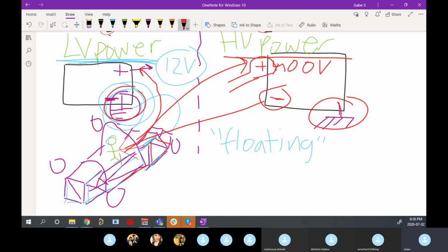So this is why you would separate the grounds, right? If you connect your two grounds, your low voltage ground and your high voltage ground, then you are basically connecting your high voltage ground to the frame, and that poses a lot of dangers to the driver. And so almost every car separates them and isolates them. Mandated by the SAE rules, probably mandated by other electrical certifications needed for electric vehicles. But you need to isolate these and make sure that they never touch for safety.